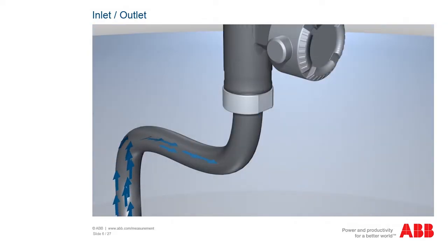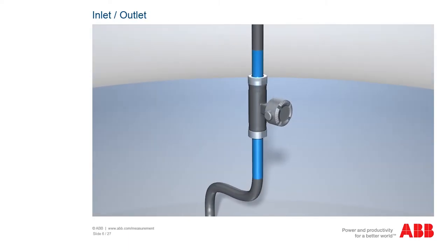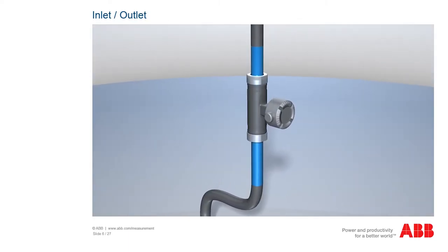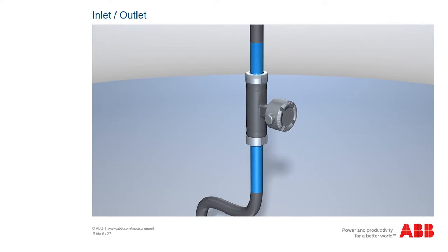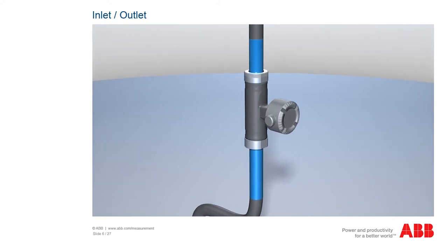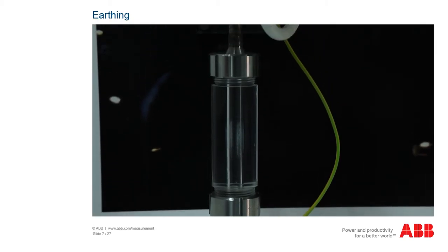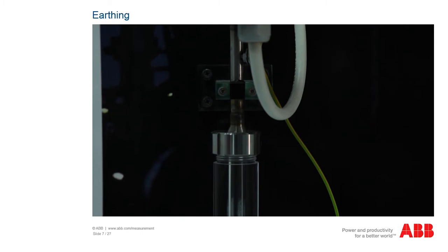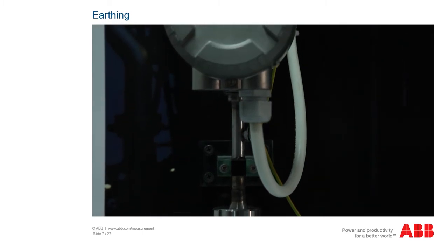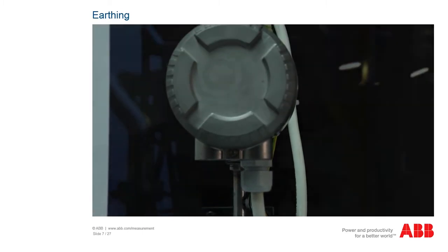The flow profile is particularly problematic if a round elbow is used in the inlet or outlet area, as here the medium is particularly heavily influenced by the double deflection. It is especially important here to observe the required straight inlet and outlet sections in accordance with the specifications in the data sheet. As the earth is the central reference point for inductive flow measurement, in the next step, check that the earthing is correctly wired and document this with photos.